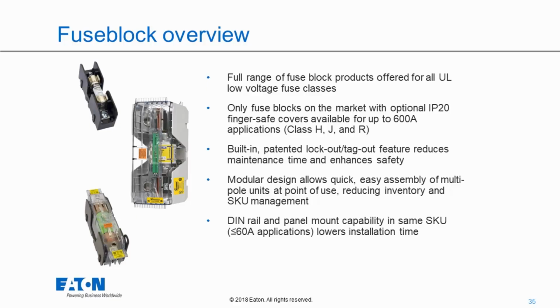So when we look at our low voltage fuses, class CC, we've got great fuse holders. This one in particular is an open type holder on the top left, but we do have the ability to put a finger touch safe cover on all of our class CC fuses now.